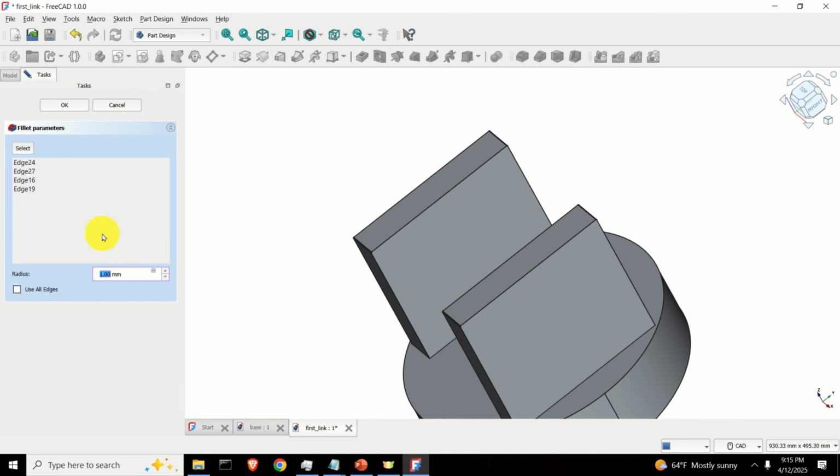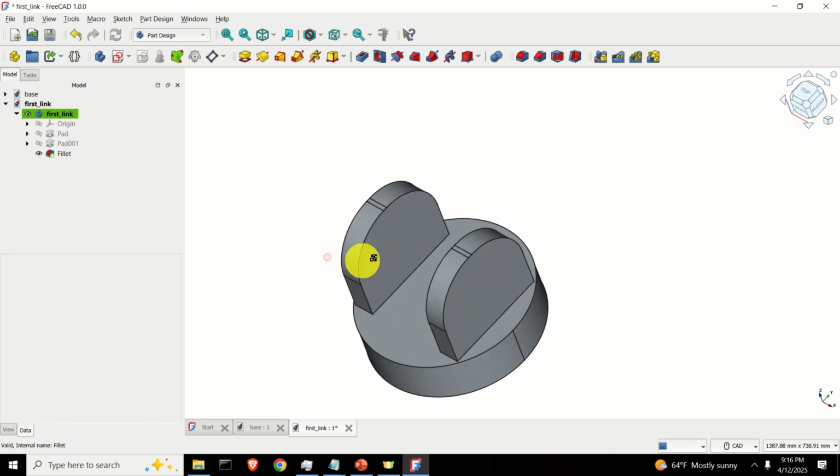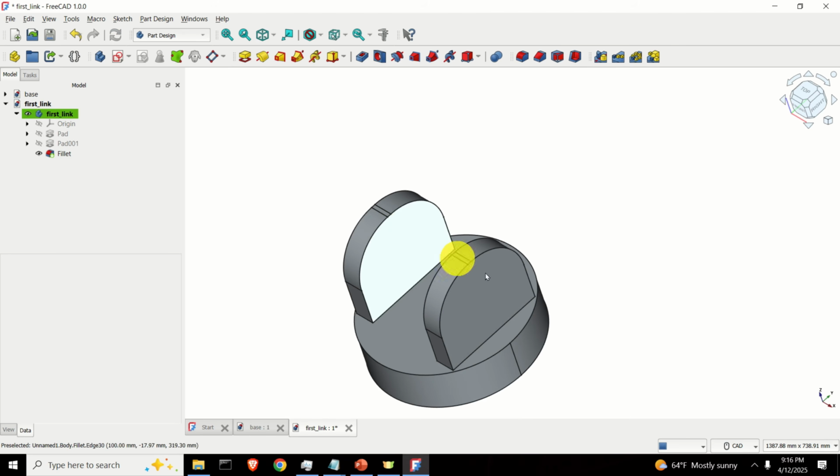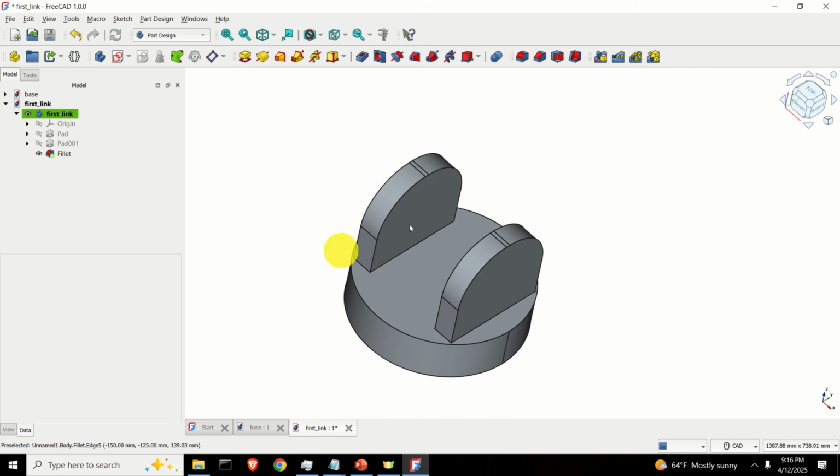Click here and select the radius of the fillets, and let's see what will work. If I now increase the fillet radius, you can see how nicely the fillets are being created, and let's see how far we should go. Let's go, for example, with something that looks like this. Okay, not bad. Let's go with 120. Beautiful. And let's click on OK, and here we are. We are almost there. Next, over here, we need to create the supporting rod, and let's learn